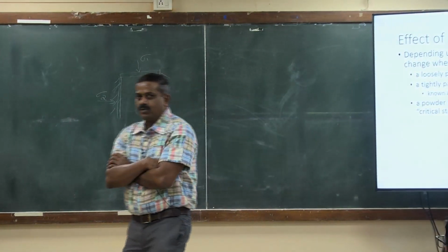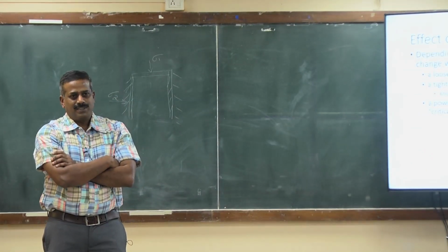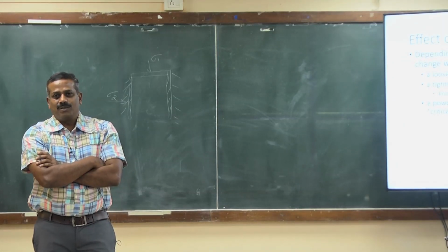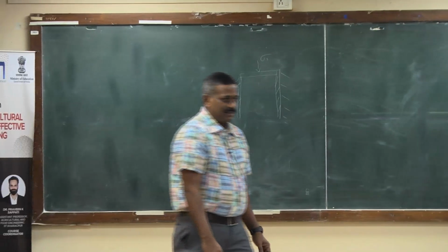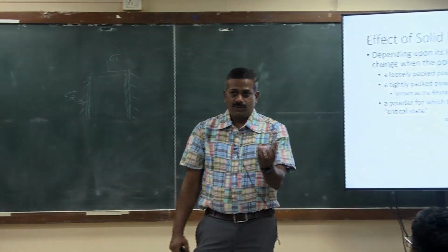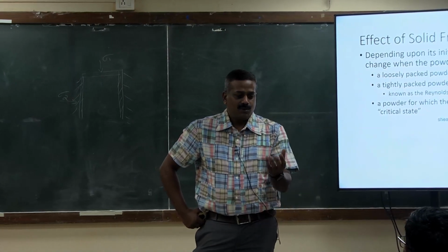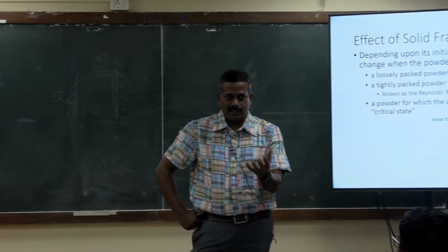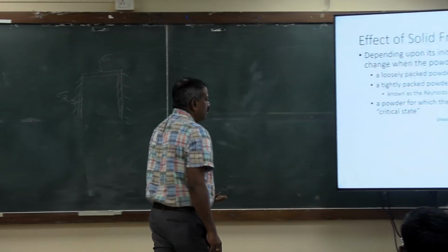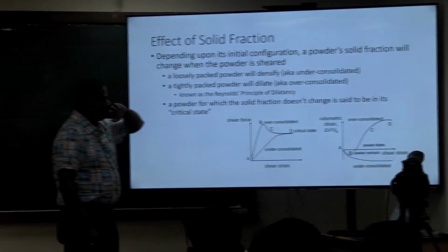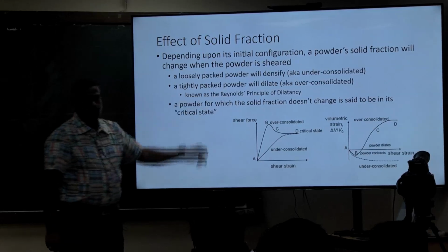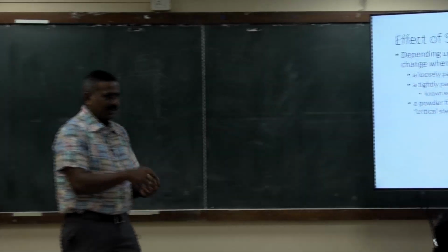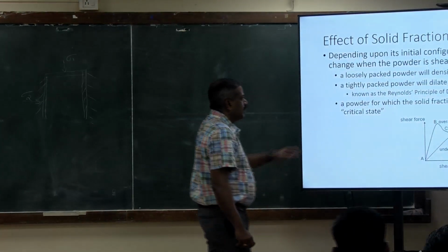So if you compact beach sand, then again, I should give you 5 bonus points tomorrow, right? When you go to any beach, if you compact it using your hands, you will feel that moving of particles inside, but still the volume you are holding doesn't change. So many powders will go through those dilations, and I'm not including it here, but the stress that leads to that dilation is called deviatoric stress.